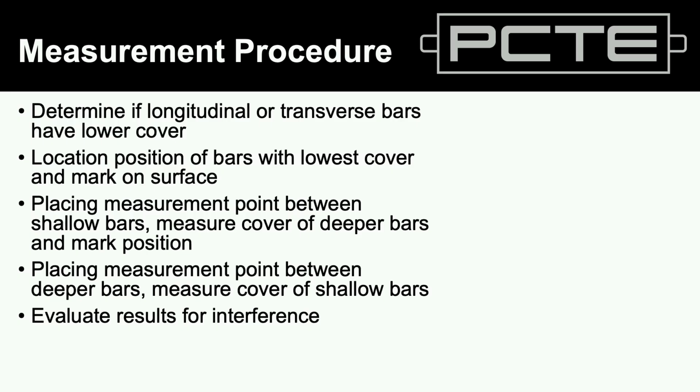You want your cover meter to be placed directly on top of a reinforcing bar and to be away from any additional metal so that you are measuring accurately. So to do that, we actually need to learn how the reinforcing is in place on site. If we're using our cover meter, and it's a reasonably straightforward locate, we can find the bars in one direction. I'm not going to take any numbers the cover meter gives me because I'm just locating the bars. And I'll do this again, moving my cover meter with its measurement point.